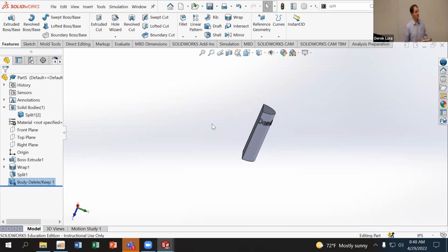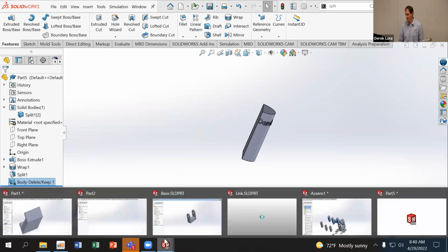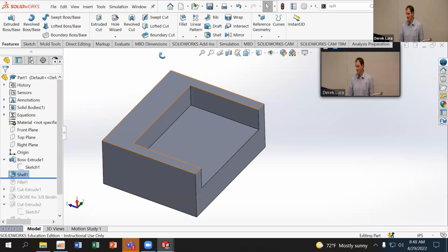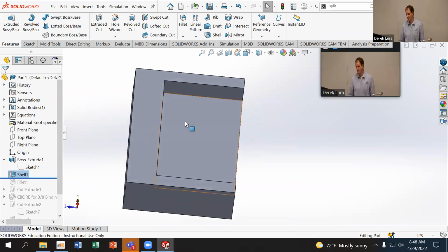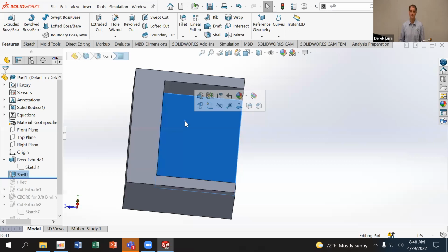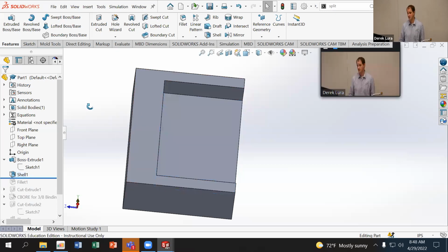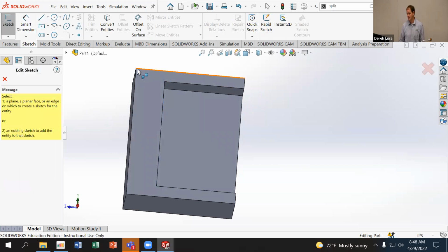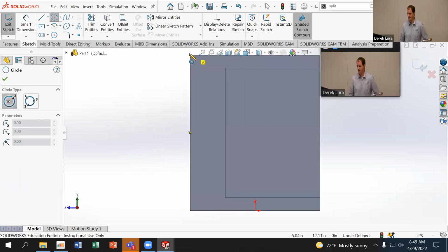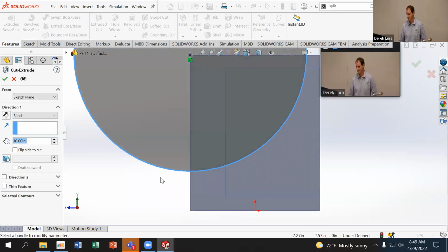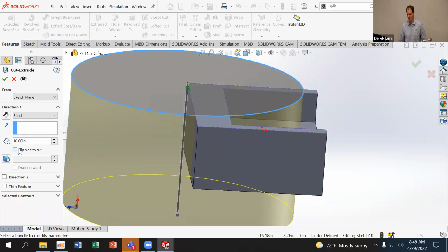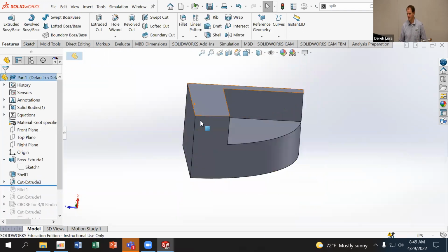This is super useful if you just want to cut sections of a part off using a reference plane. So if I have something like this here, and I want to cut off an angle, or say a circle or something, I'm not coming up with good examples because all of these would be more easily achieved with just a cut extrude, but let's just do one for the sake of showing you how you can do it. On here, really what I'd probably do is just an extruded cut. And you could do something like that.